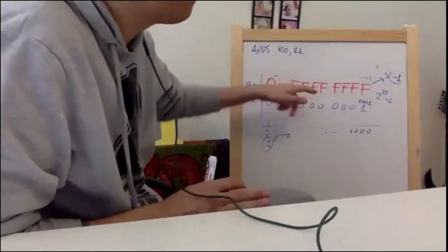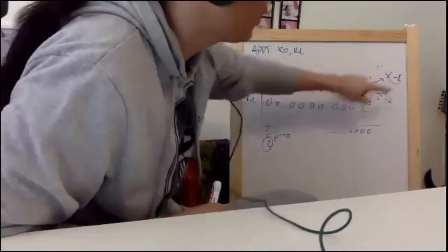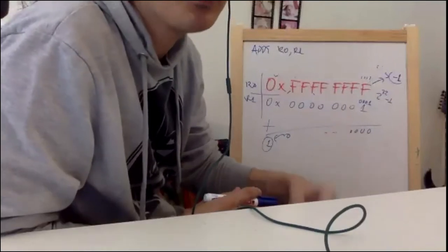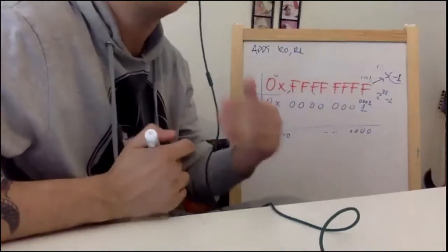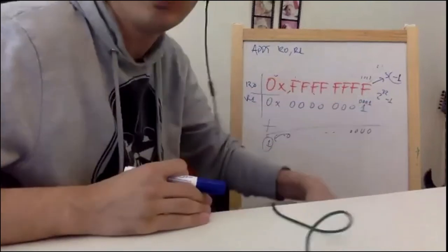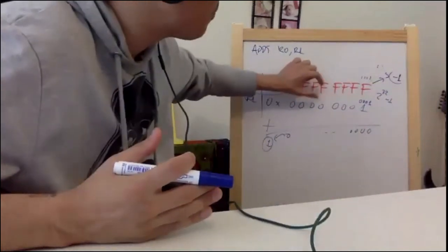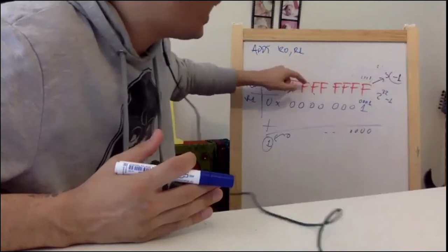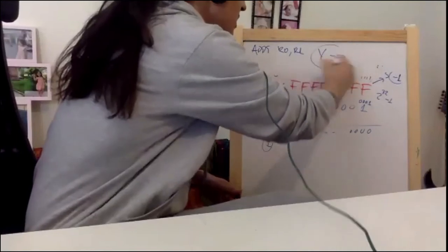Let's now assume that this was a negative number. What is the negative number? Minus 1. What is this number? Plus 1. Minus 1 plus 1, which is that number? 0. In the actual summation, is there a carry? I mean, which means the result of the operation, can I still represent this number using 32 bits? Yes, it is 0. You can represent it using 32 bits. So if this is a negative number, if I'm assuming that these are signed numbers, I can still represent the result. That's why this is not an overflow, guys. V should be 0.